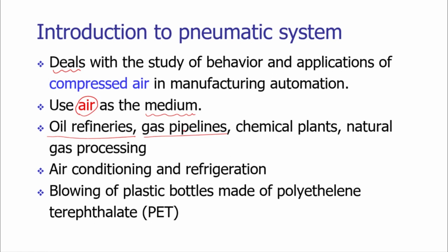So in the petrochemical industry, basically we cannot use electrical energy, as it may lead to generation of sparks, and that may not be safe for the processing application. So in these situations, compressed air, which is harmless, the chilled compressed air or the compressed air at the normal temperature, will be very useful for the sensing applications.